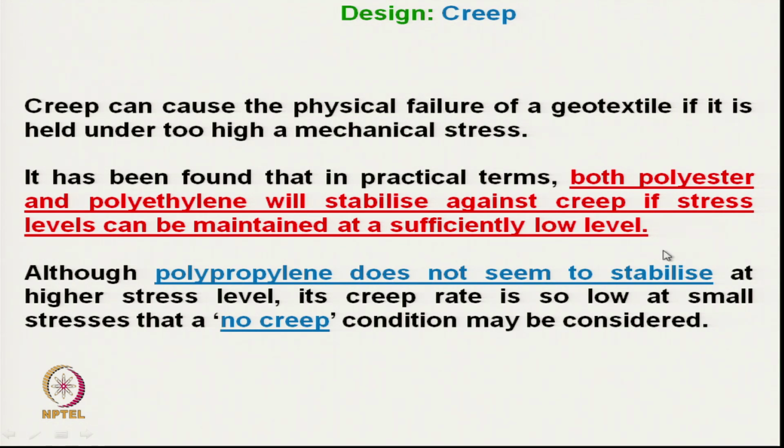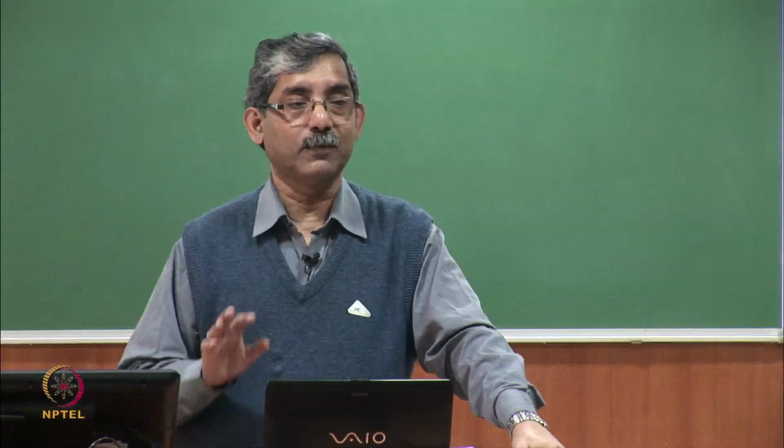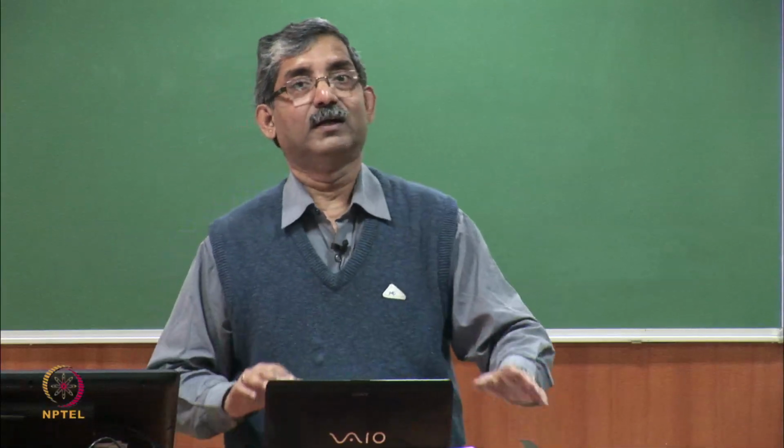Although polyester and polypropylene show higher creep at high levels of load, if we maintain the stress level low, there can be a situation of no creep condition.